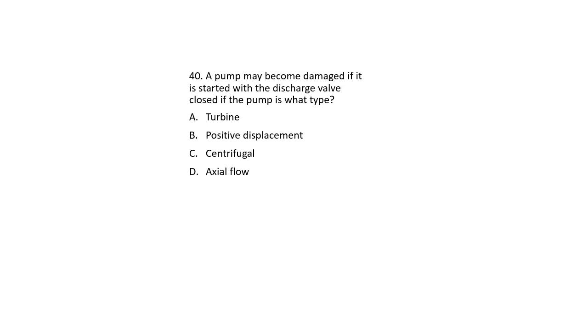A pump may become damaged if it's started with the discharge valve closed if the pump is what type of pump? Turbine, positive displacement, centrifugal, or an axial flow? And the answer is going to be B, positive displacement.